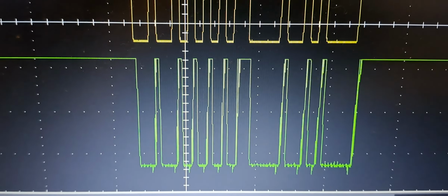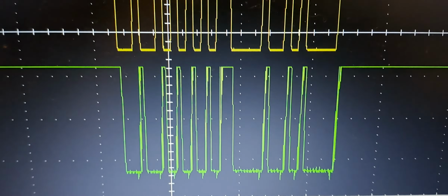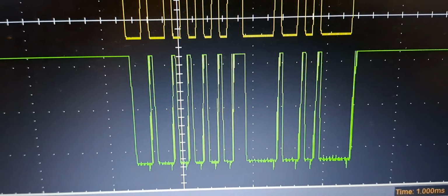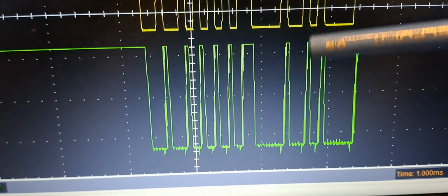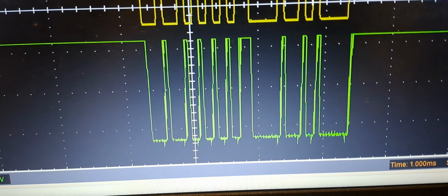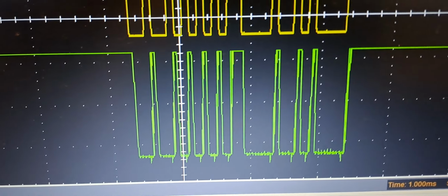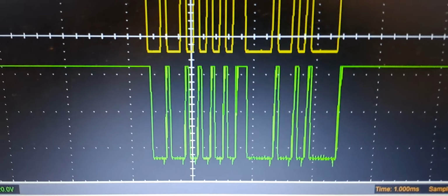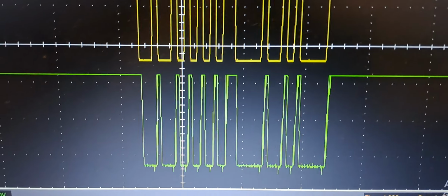Actually, I did not test it with Arduino Uno because it is generating a voltage of 9 volts. So I need to design another circuit so that the amplitude of this waveform will be reduced. Some clipper I want to design. So you can see here this is the output after using the op-amp comparator. So let us see the output after the envelope detector as well.